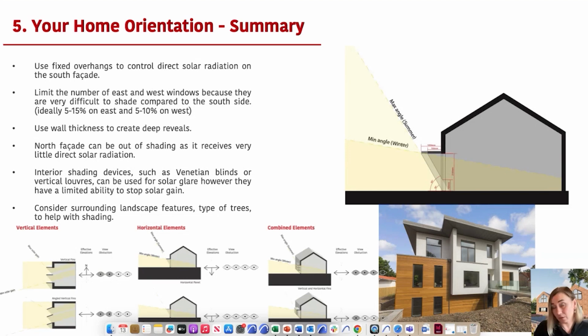So you can opt to put retractable shading devices on the outside of your window. However, if your predominant views are towards east or west, you probably won't be using those devices. So the last resort that we tend to go to is to upgrade the window G value.